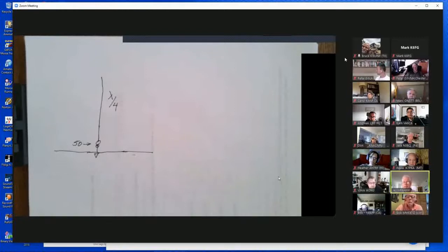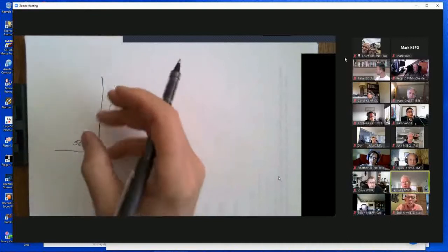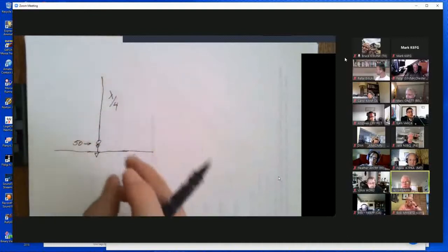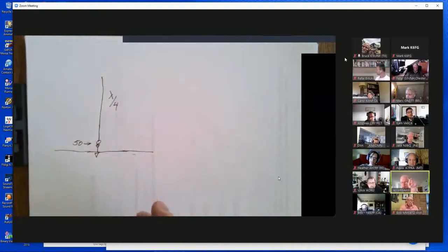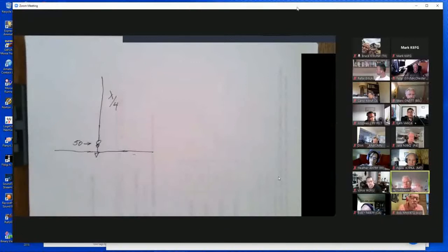The reason is, as you go up in frequency, less of the energy flows in the wire, or the current flows in a smaller and smaller area. The inside of the wire is shielded by the outside of the wire. You know how copper shields, they shield energy from crossing over and keep one part of the circuit from talking to another part.